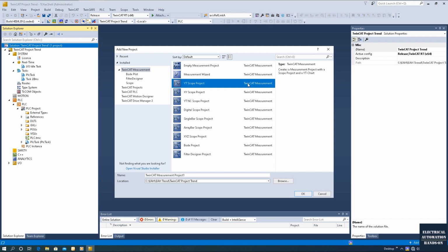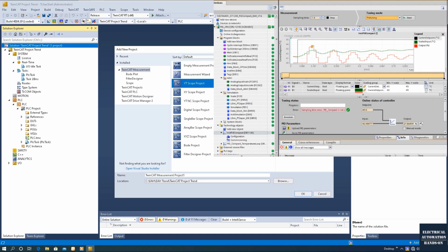Another good trace function comes from Siemens TIA Portal. A good feature of the trace function in TIA Portal is the sample time. The sample time could be the same as the cycle time of the PLC, so that could be very fast. However, it's limited in length because the trace function stores all the data internally in the PLC hardware.